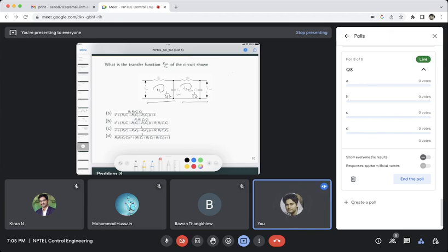So you can directly work in the Laplace domain. Whenever R is present, it is just R, because I simply multiplies with it. Whenever a capacitor is present, you take 1 by C times the integration of I, so it will be 1 by C1S into I(S). And when an inductor is present, it will be L di by dt, and the derivative is S times I(S), so it will be S times the inductor value L if there is no initial condition, or if there is some initial value, you just subtract that.